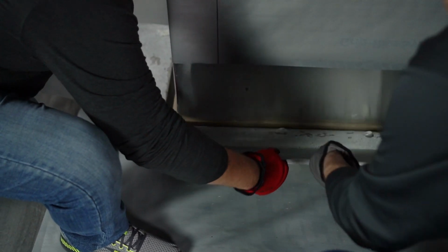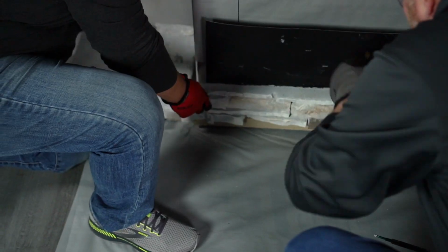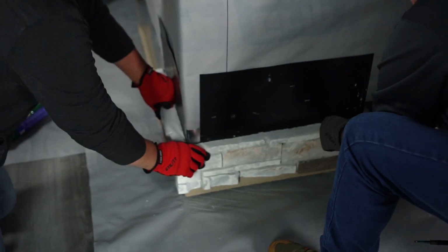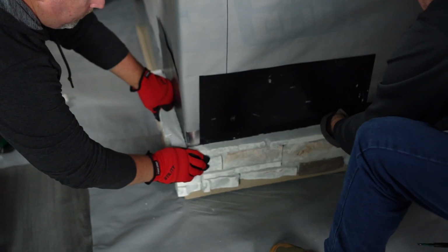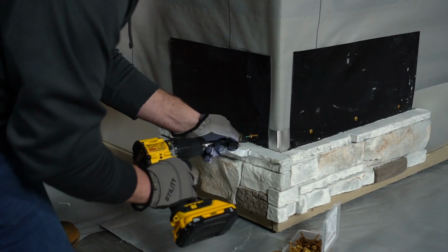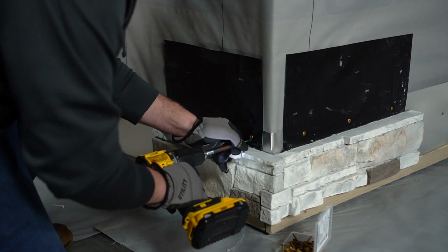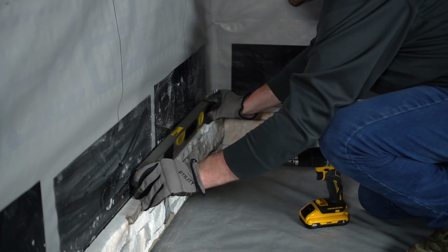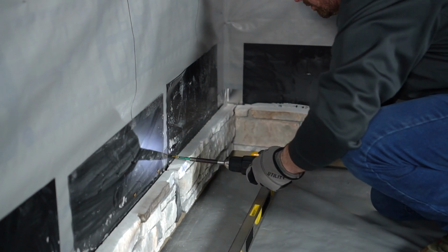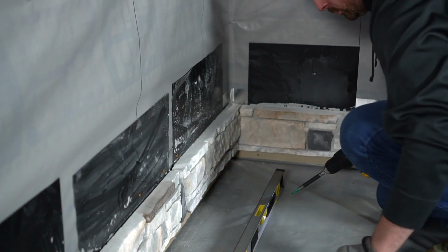Position first flat on the leveling board, water table, or align with the snap level line, and firmly butt up against the corner of the transition material. If there is an outside corner, always start at the corner. If there are outside corners on either end of a wall, start at each outside corner and work your way to the middle. Using a short level, ensure the panel is level and aligned with the adjacent corner of trim.